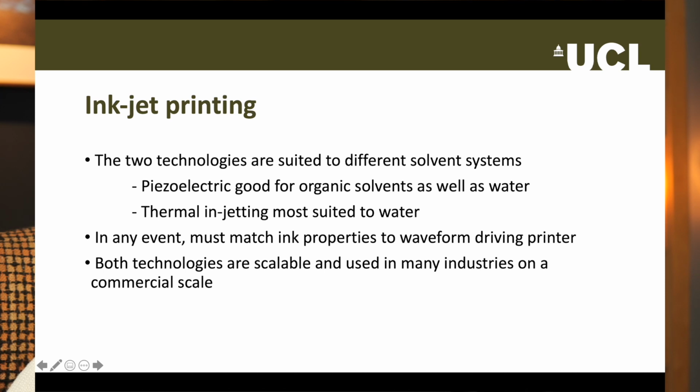Although similar in most respects, the two technologies are suited to slightly different solvent systems. Because the temperature rise in a thermal inkjet printer can be high, it is more suited to printing aqueous solutions because they won't boil and their high surface tension needs a considerable mechanical force to overcome.